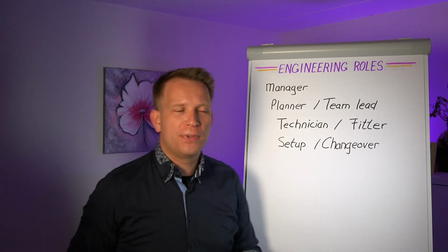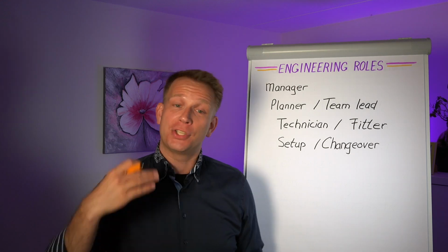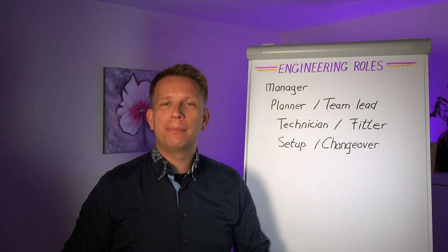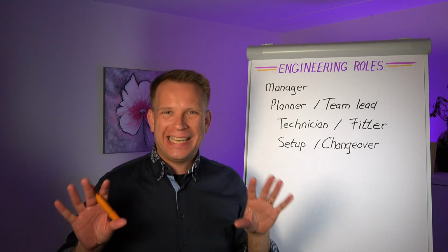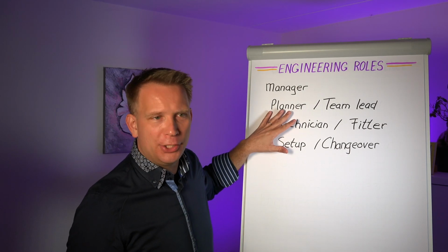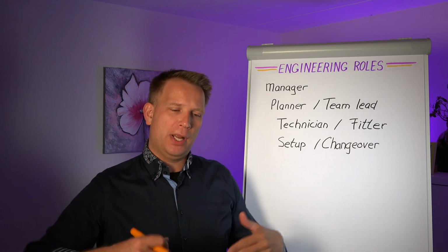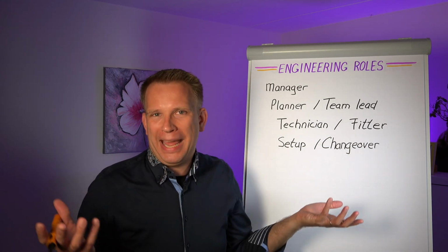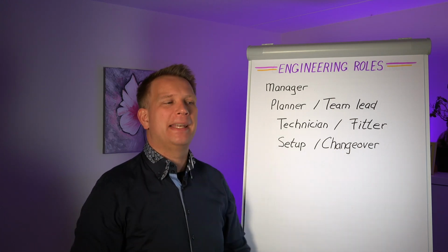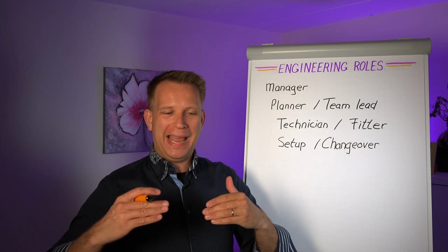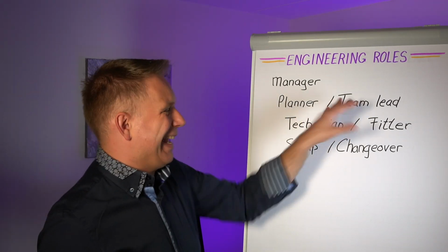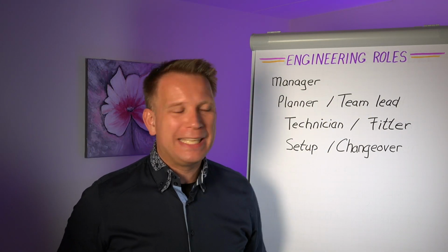So what you will often see is that the shift technicians and also the day technicians are led by either a planner or a team lead. In a bigger organization, these are distinct roles. You will also see things like a short-term and a long-term planner being used, where the long-term planner plans the next planned preventive maintenance and inspection stuff, the big planned downtimes. The short-term planner plans the work of next week and makes sure that materials are there. And that can be separate from purely a team lead.